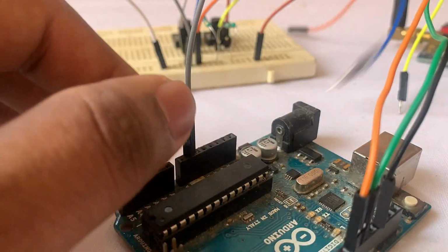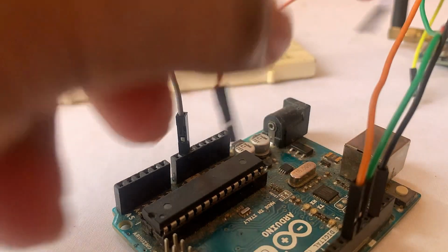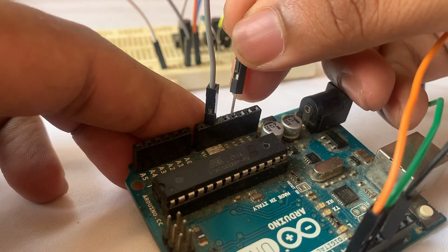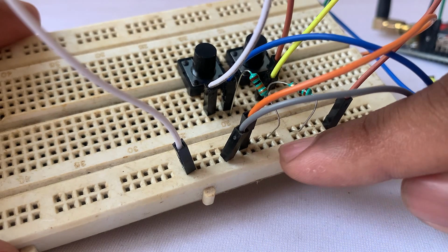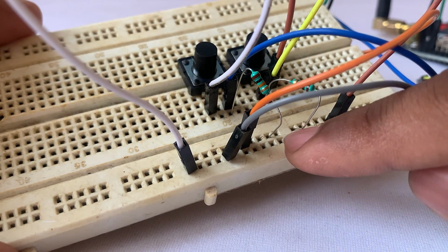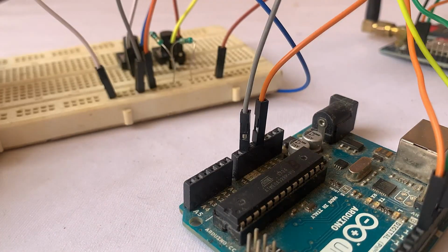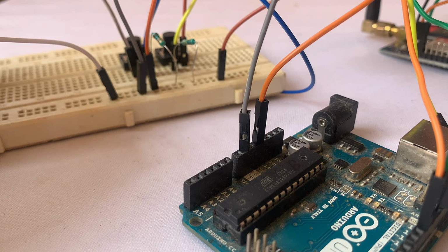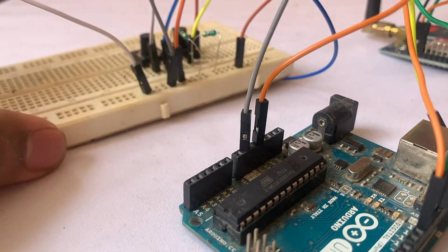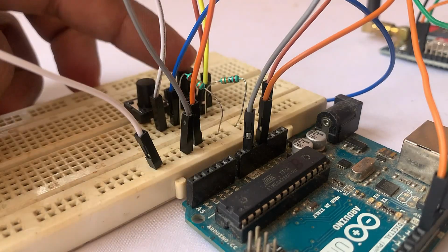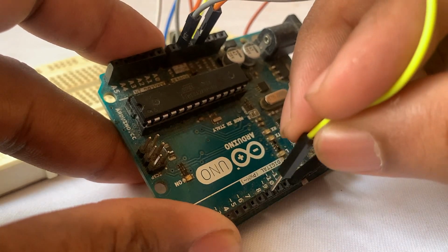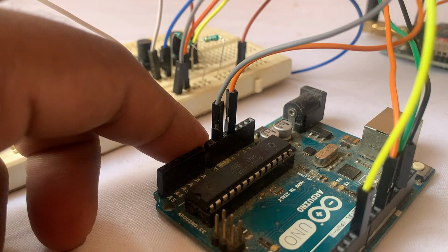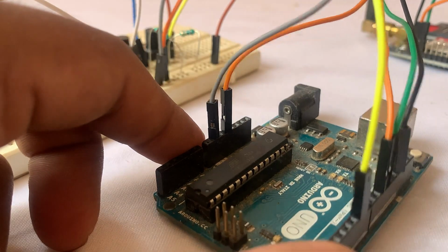You can clearly see, and this orange wire is the positive rail of the breadboard. So I'm just connecting this orange wire to the 5 volt of Arduino UNO. So you can clearly see I'm just making this rail, that is the gray wire rail, as ground of the circuit, and the orange rail as positive rail of the circuit. And regarding the ground connection of push buttons, I have already made it in the breadboard itself, and I'm just going to connect this push button, that is this push button yellow wire, to the digital pin 6 of Arduino UNO, and the second push button I'm just connecting it to digital pin 7 of Arduino UNO.